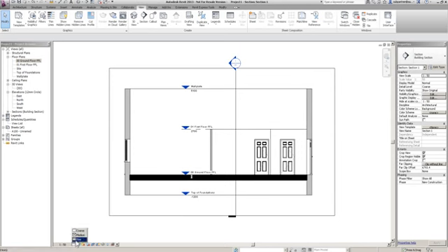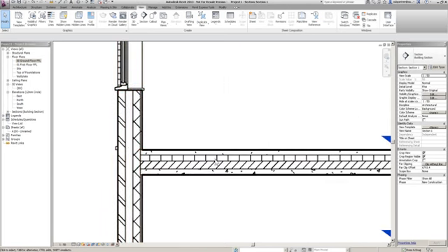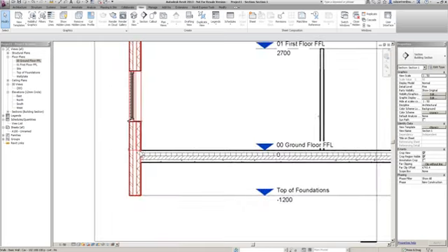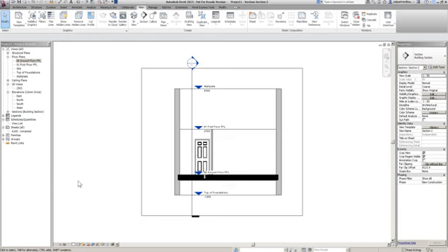Okay, I'm just going to change it to a fine detail so I can see what's going on in the wall constructions. And you can see this is basically the zone for my beam and block floor, and you can see how it's butting along this external cavity wall along the blockwork. Okay, let's flick to this section just here to see what's going on. Again, I'm just going to turn that to a fine detail.